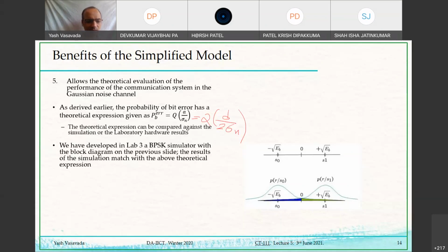The reason I say controlled is because we would need to know what the transmitted bits are. Then we will get the received bits and we will compare the transmission with the reception, and we can calculate maybe in Excel or Google spreadsheet how many bits are correct, how many are wrong. And that way we can determine what is the bit error probability.